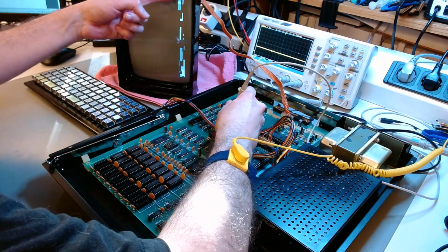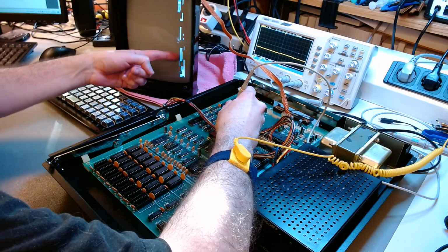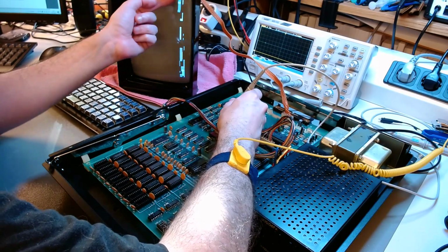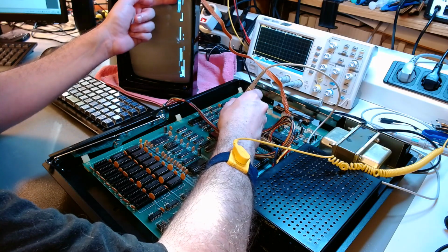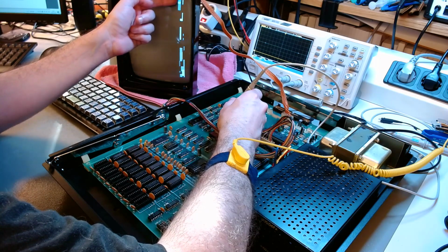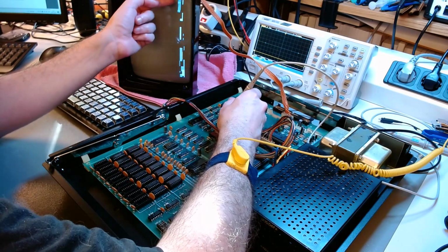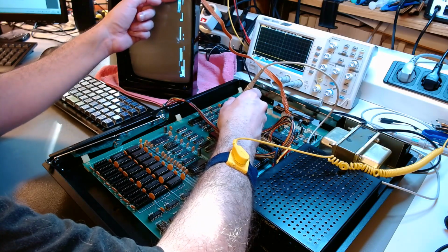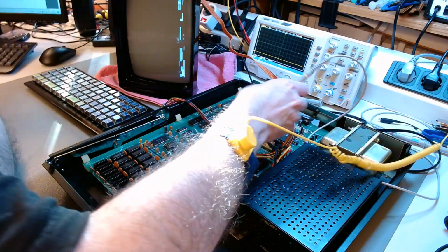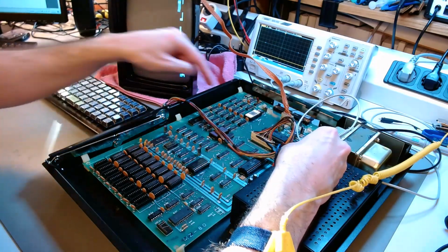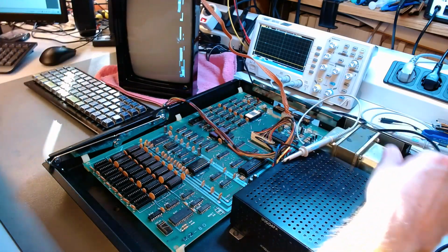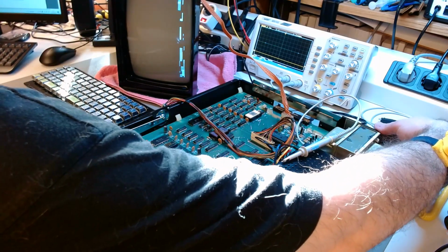That explains why we only have lines, because it loads 8 bits, but then it doesn't shift, so it keeps showing only the first bit of the character line on the screen. If that bit is a 1, then you have a full line. If it's not a 1, it's a 0, then you get 8 times 0. So the problem may not even be the shift register itself, but the missing clock input, probably from the modifications. Let's have a look.